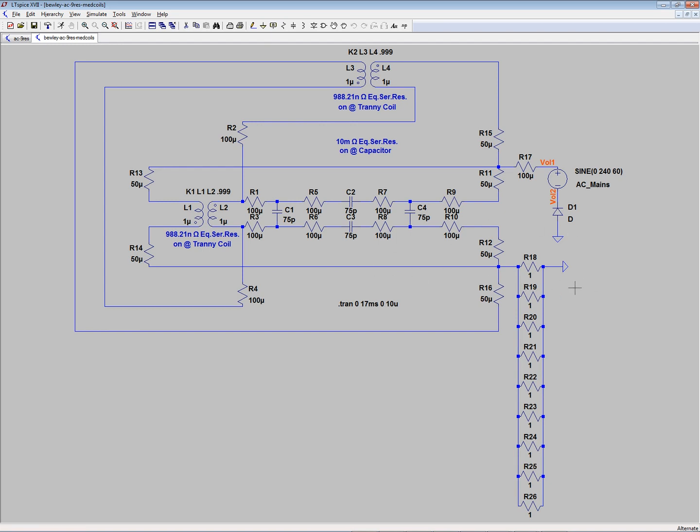and also I have another version in Paul Falstad's simulator. Despite the fact that these resistances here, all these solder joint resistances and the coil and the capacitors, whatever, they're fixed, right? And they add resistance in series. So it doesn't matter what the equivalent series resistance of all these parallel resistors is, inasmuch as they keep dropping. The more I add in parallel, the lower the singular series resistance equivalent to all these parallel resistors. It doesn't matter if this keeps dropping.